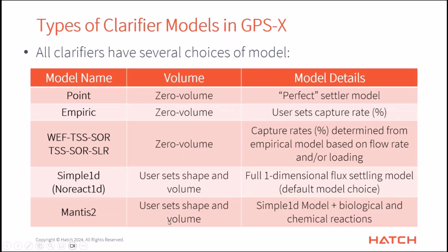That's not the case for these ones that have volume. There we're modeling the actual residence time of the reactor or of the clarifier itself. So these first three here, these zero volume ones, they're instantaneous, they're nice and easy to use. We have a perfect settler model that basically captures all the solids, or empirical, which allows you to set